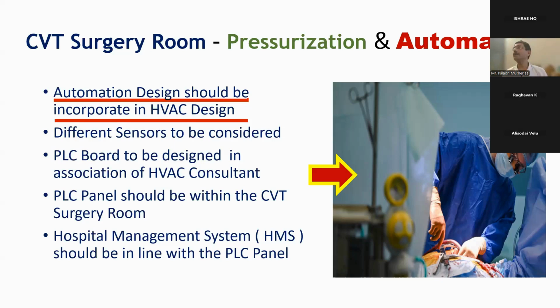See, our ASHRAE guideline is set for a minimum of 20-25 ACPH. But the American Thoracic Surgery Associations recommend a higher ACPH, because, it will take a lot of time to explain, these types of surgery take 12 to 14 hours.